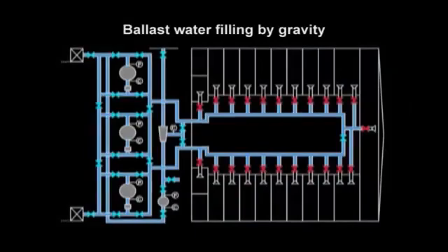Now we begin filling ballast water by gravity. Put the valve line up in the proper order to bypass the ballast pump.